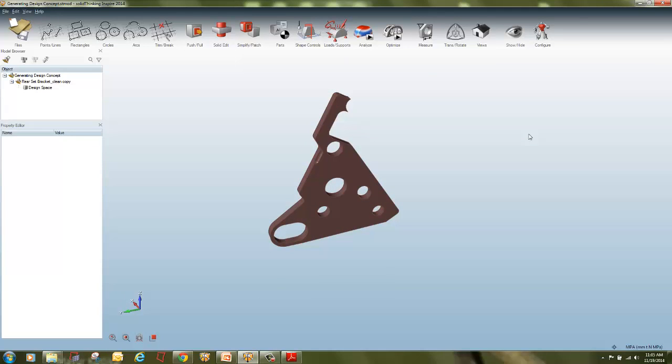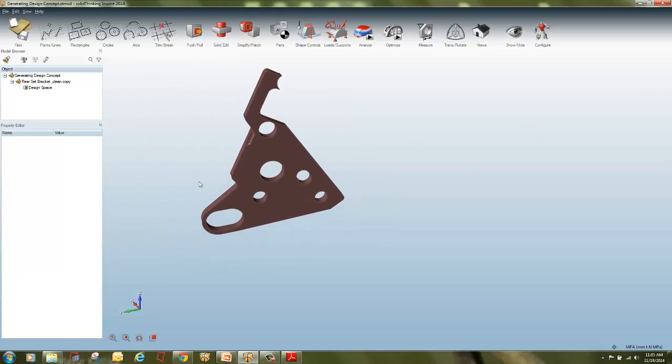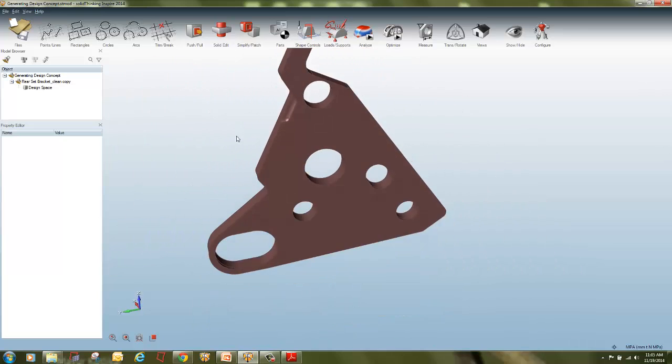Then zoom versus smooth zoom. The scroll wheel on the mouse will zoom about the mouse cursor, wherever it is positioned on screen. To perform a smooth zoom about the screen center, press the Alt key while dragging with the middle or right mouse button. So with the wheel you can zoom in and zoom out anywhere.